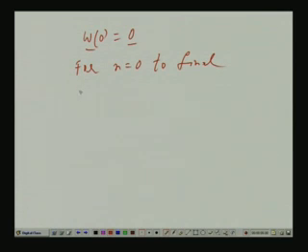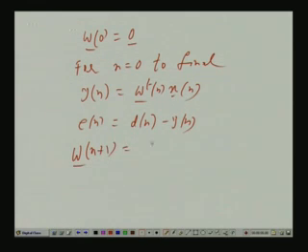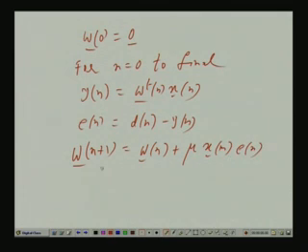What happens? You find out first the filter output y n as w transpose n x n, then E n as desired response minus y n, and then you go for the next set of weight coefficients, filter coefficients. Okay. And so, this is a real time algorithm.